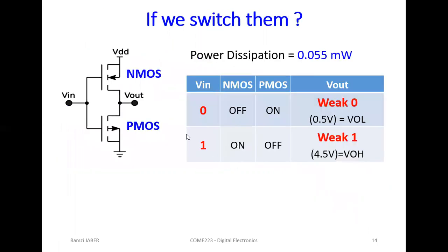Else you have to add or subtract 0.5 volt. If we put PMOSFET to the ground, we will add 0 plus 0.5 volt. If we connect NMOSFET to the VDD, to the power supply, we will subtract 5 minus 0.5 volt. The internal diode here is 0.5 volt.